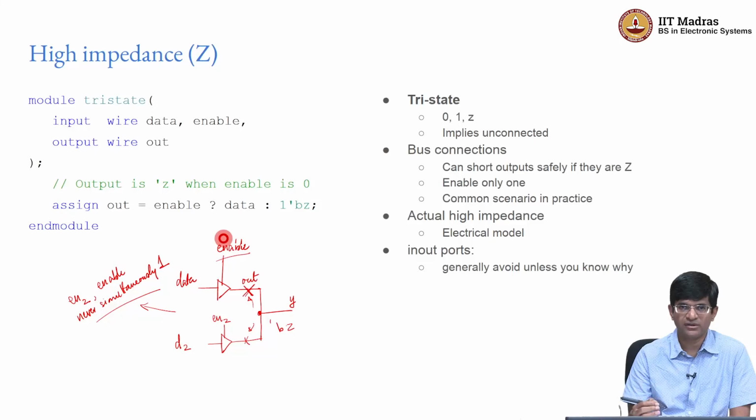So at least to start with, I would strongly suggest simply do not even think about inout ports in Verilog. Just forget about the fact that they exist. You should not be using them unless you are extremely clear about why and under what conditions they are going to be active.